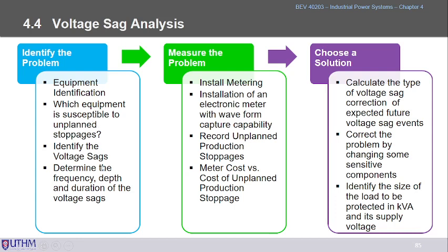And we try to find as well the voltage sag magnitude. So how much is the voltage sag magnitude? And that means we need to determine the frequency as well, so the durations of the voltage sag. And after that, we try to install the metering, so we do some measurements to measure the waveforms. We capture the waveform, so that we can choose a proper solution for that.